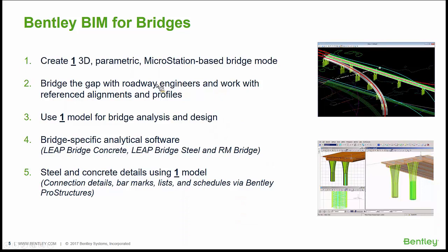We do kind of bridge that gap between the roadway engineers by allowing the bridge folks to simply reference the alignments and profiles and reference the terrain model. That way, if a change is made to, let's say, a profile or a terrain model, the bridge will automatically inherit those updates and can change geometrically based on any of those changes.